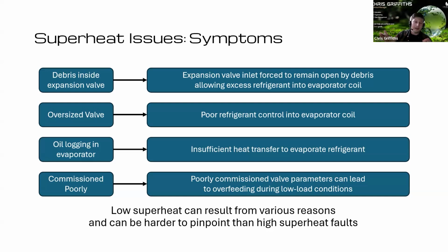So where we have low superheat, I always consider it a lot harder to pinpoint the real cause than high superheat faults. Yeah. In some of the intro to CO2 courses, I have a lot of technicians who come in and they're just starting to learn about CO2.